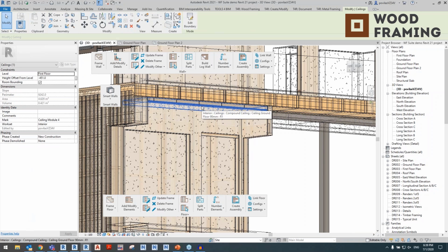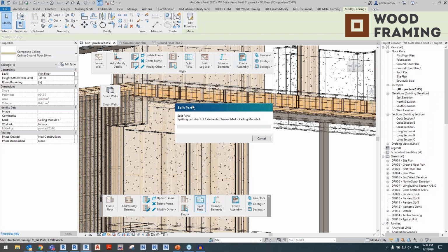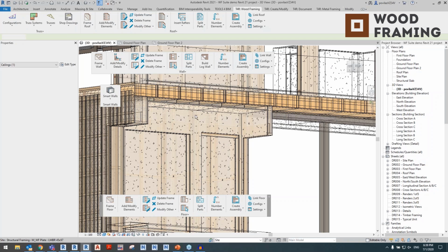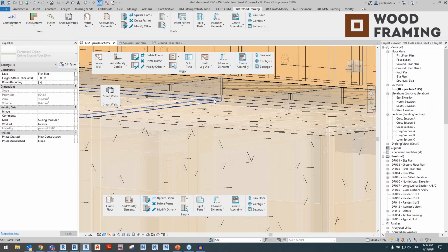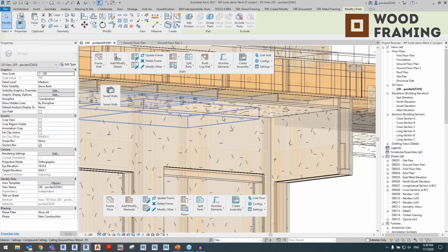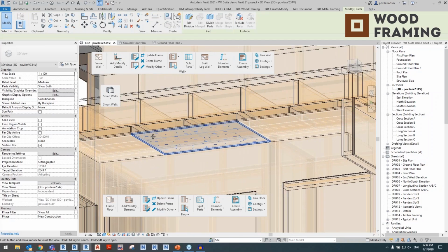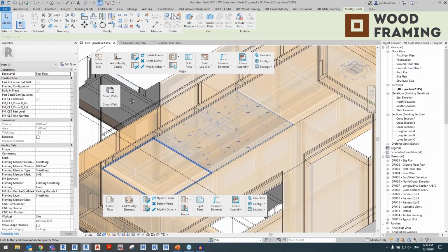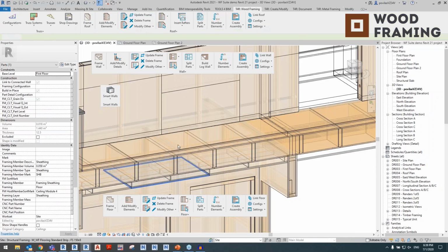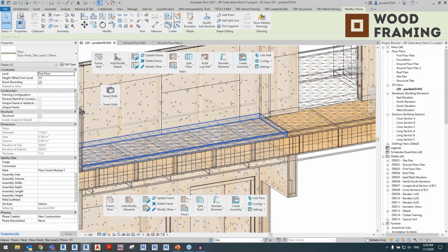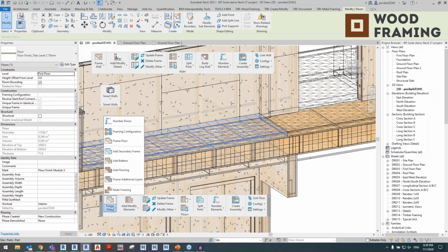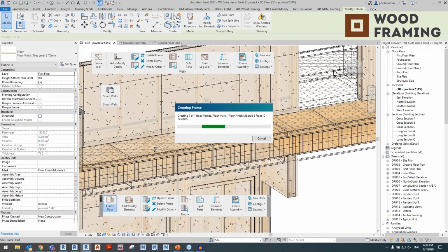Make sure you select the entire ceiling, not the parts, and then what we're missing, just splitting parts for that to get our 2 layers of plasterboard. We can also provide some detailing if we need, like clipping on plasterboard to metal profile detailing. And right here I have my floor, additional floor, so that also has battens.